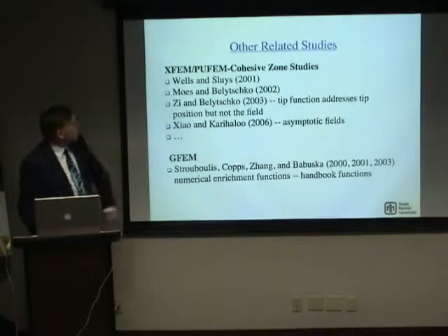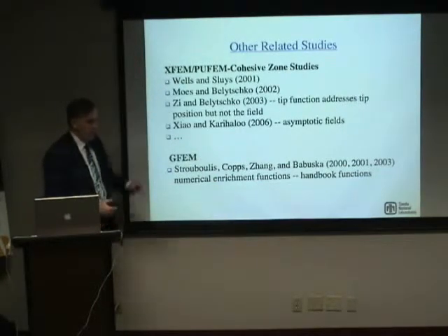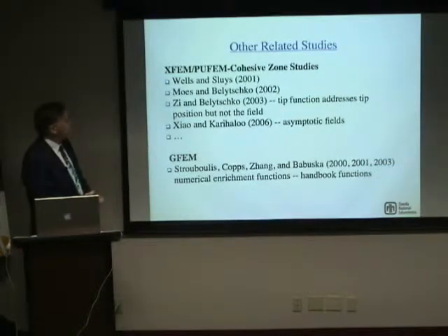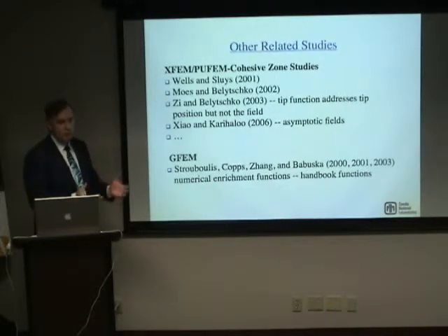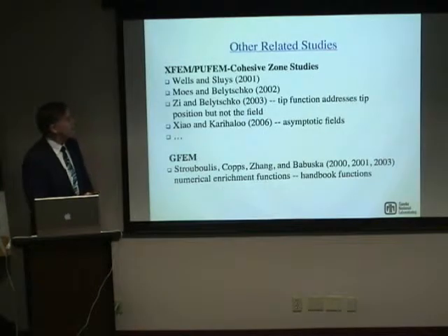Okay, XFEM, PUFEM, cohesive zone studies. So we started this work back in 2001, before the paper of Wells and Sluys came out. Well, we actually started in 2000. And our intention was to try to come up with a way of enriching the cohesive crack problem, and not linear elastic fracture mechanics.